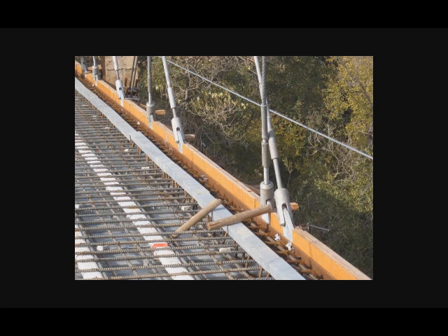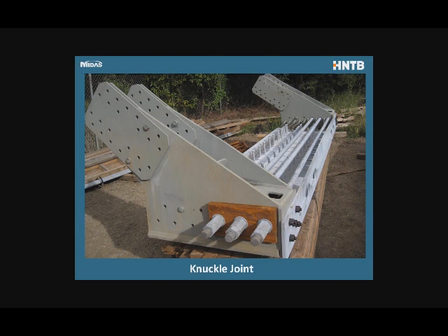On top of that, we also have plenty of rebar in the deck, so there's another level of redundancy. The rebar alone can take a good portion of the tie force. So we really have 3 tie girder systems at Happy Hollow.